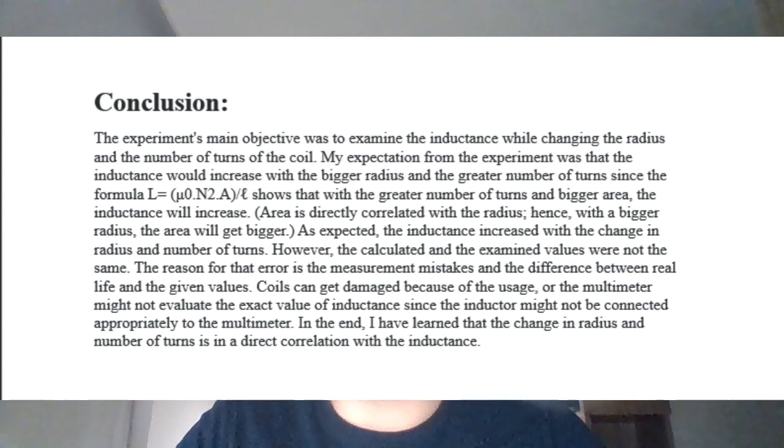However, the calculated and the examined values were not the same. The reason for that error is measurement mistakes and the difference between real life and the given values. Coils can get damaged because of usage, or the multimeter might not evaluate the exact value of inductance, since the inductor might not be connected appropriately to the multimeter.